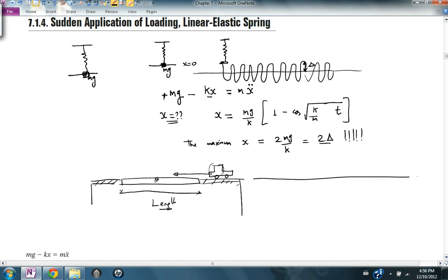For longer bridges, it can be considered more like a static state, because it takes the car a really long time to approach the middle of the bridge, which is equivalent to saying that I'm applying the load very slowly. And for the design of such bridges, I have to apply some dynamic factors. As you can see here, the maximum effect that I can get is twice.